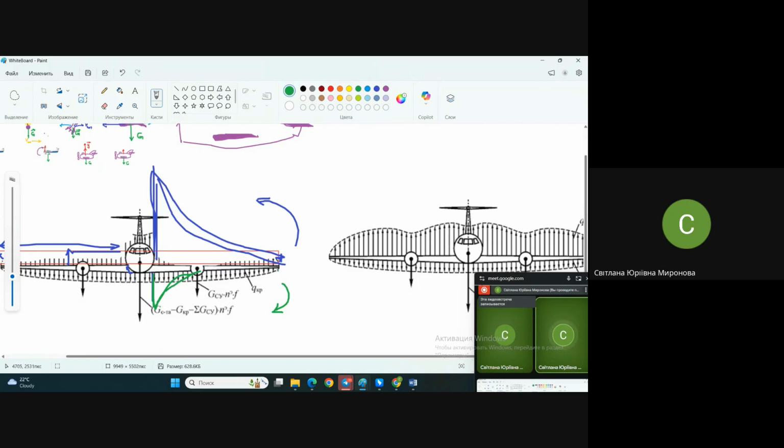In the superposition of these two lower diagrams, which is the final diagram, we have some growing of bending moment, and since the moment where the engine is, it starts growing not so sharply. It's like reducing the peak of bending moments, inner responses, inner stresses inside the structure. So the inner loading of the structure will be not so dreadful, not so significant.